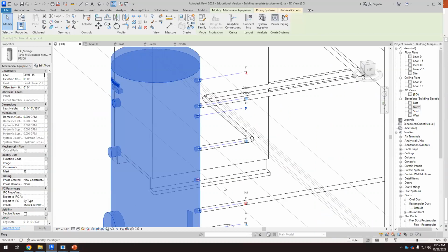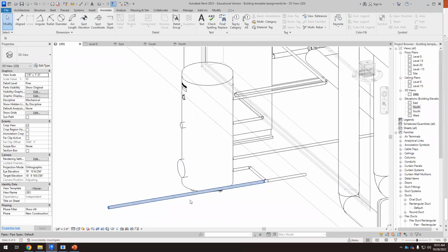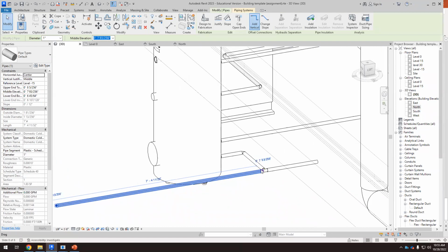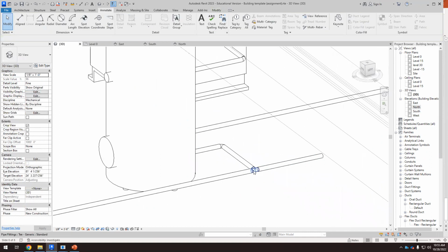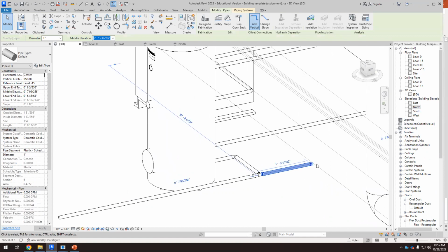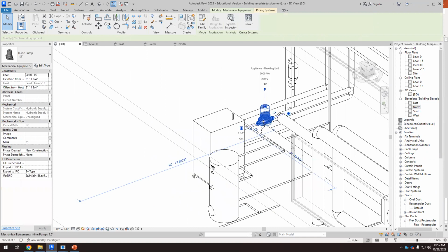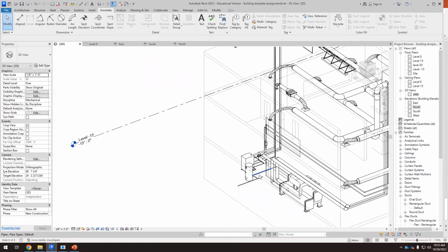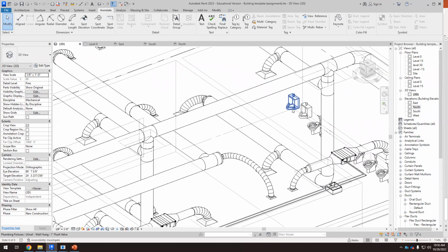From this pipe in REVIT, so there's a pipe that comes from outside the building. Part of this pipe goes to the water tank, and the other part of the pipe will go to the fixtures. Okay, so here we have this T, and that goes to the tank. And this one, we need a water pump here. So we need to insert another pump like this, and that will go to the fixtures that are all the way here.